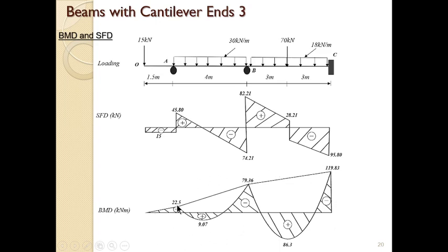Notice that on the other span, the cantilever span, there is no load, so there is no simple support moment to superimpose. It's just the support moment that is here. This one is usual, this one is usual. So that is it for the case where we have a cantilever.